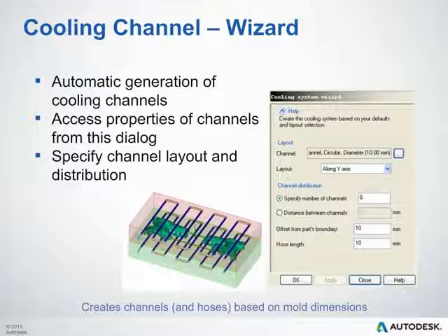Now, you can see here that there are some cooling channels as well as hoses, which are those gray features. What's a cooling channel and what's a hose is largely dependent on the size of the mold block you created. So, as I mentioned before, you need to make sure that your mold block is large enough to contain everything you need. These hoses are great, and they're not breaks in your cooling channel, but hoses are simply factored in to the pressure calculations. So they do not factor or influence the heat transfer at all out of this mold.